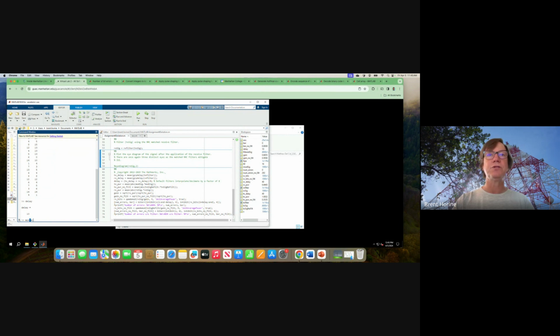One of the things I found useful is to look at my min and max of X, and it should be 0 to 15 because that's how we created those using that random number generator with that spread. And then also look at your RX bits. Before I got the gains all worked out, I would see the minimum of RX bits would be 5 or something like that. That gives me a clue that the demodulation process isn't working as expected, right? So, okay, hope that helps.